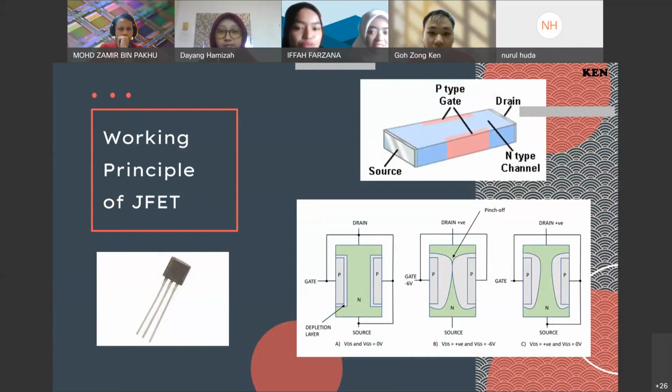For the JFET transistor diagram, there is a channel. We can differentiate it by looking at the polarity of the gate terminal and the channel. We can also see this JFET containing four important components. There is P gates, drain, and channel and source. Each of them play important roles in controlling the current flow in channel. So, how does JFET control the flow of current in the channel?